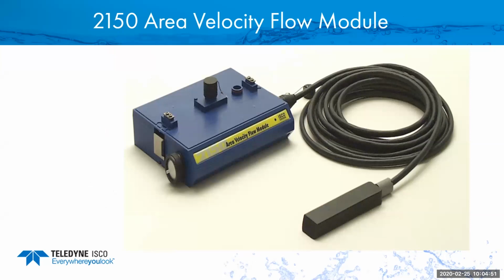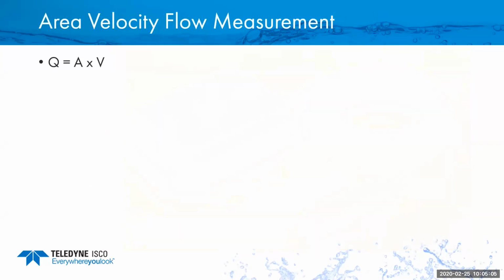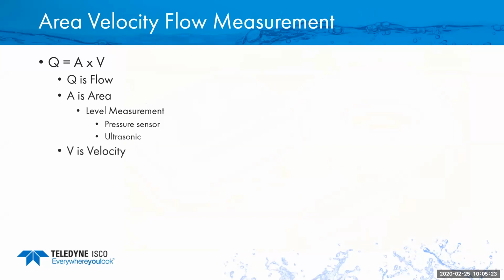The 2150 has been around since '99. We sell a lot of these, and they're really the workhorse of the industry. They're designed for more temporary monitoring, and they use a standard area velocity type sensor. Let's talk about area velocity. Q, your flow, is equal to the area, which is calculated using some level measurement technique. We typically use a pressure sensor on a 2100, but you can also use ultrasonic. We use ultrasonic on the laser.